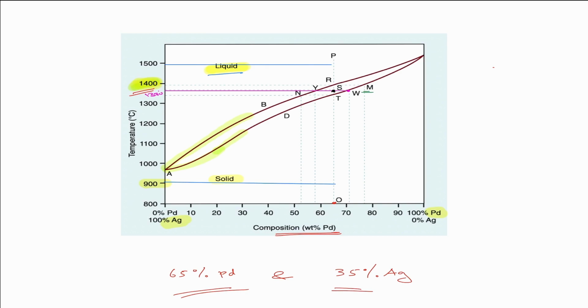And that has got a different composition. That's what I want to tell you here. It has got a composition which corresponds to the point P0. It is solid and liquid at this particular phase. But when it reaches a particular point where it is much more toward the solid, that is point W, the composition is different. The composition is somewhere in the 70 range.